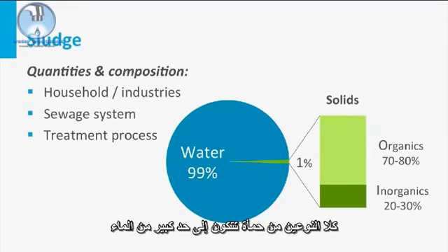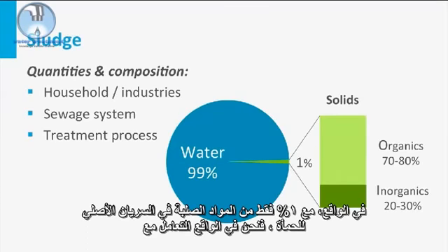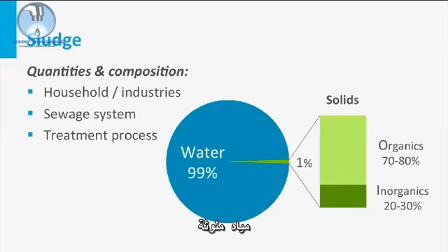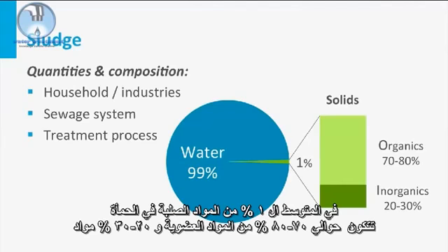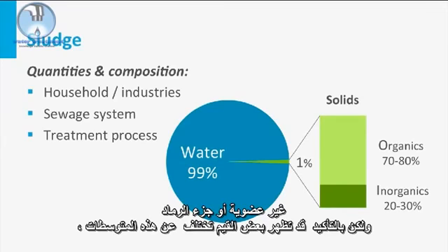Both types of sludge largely consist of water. In fact, with only 1% of solids in the original sludge stream, we are in fact dealing with polluted water. On average, the 1% sludge solids consist of about 70–80% organic matter and 20–30% of inorganic residues or ash fraction, but values deviating from these averages certainly appear.